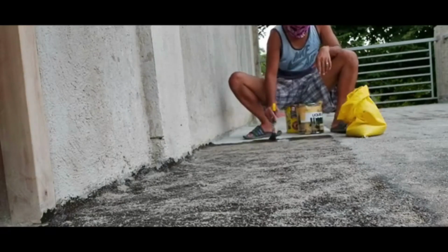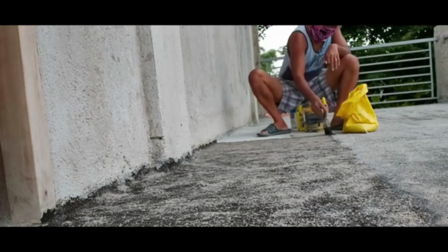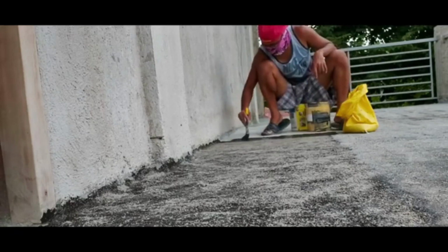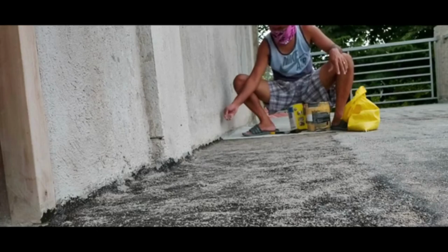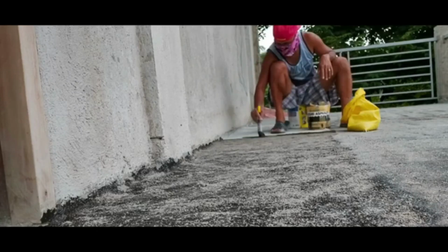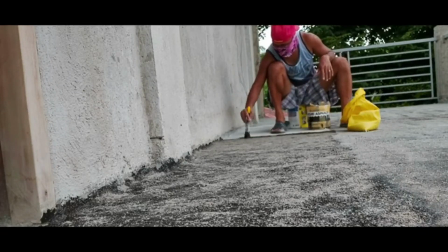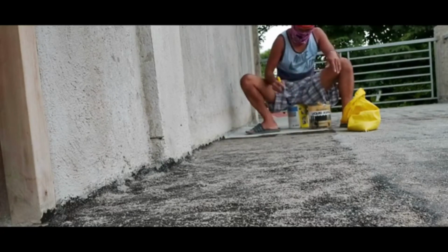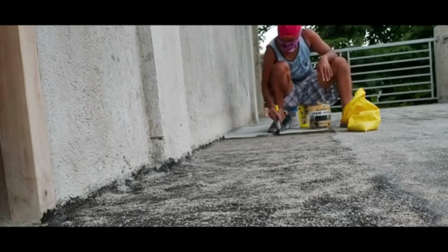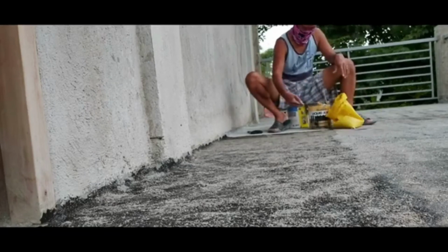The concrete finishers apply a sack-rubbed finish by wetting the concrete surface, rubbing a thin mixture of sand, Portland cement and water over the surface with a piece of burlap or sponge float, and then rubbing a dry mixture of sand and cement over the same surface. Then the finishers have completed the sack-rubbed treatment. The surface has the appearance of sandpaper, but all holes have been removed.